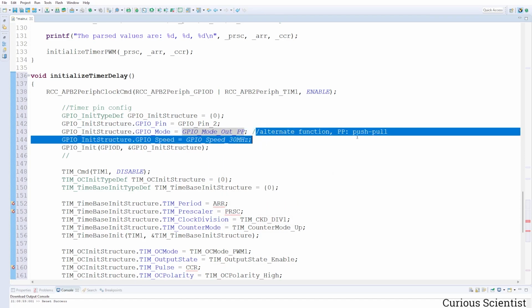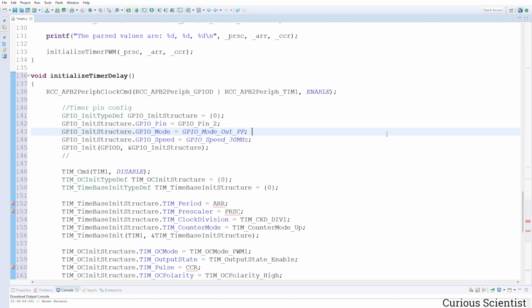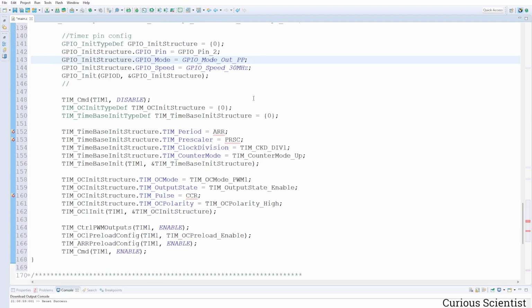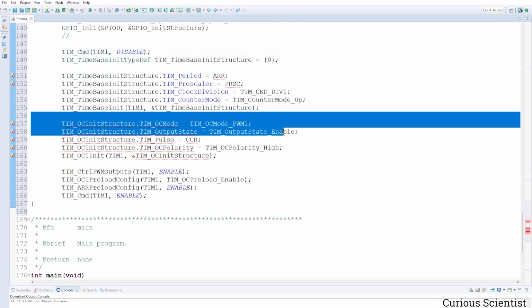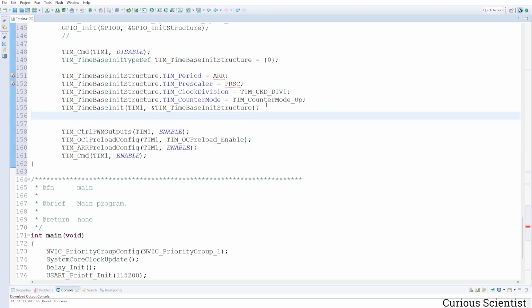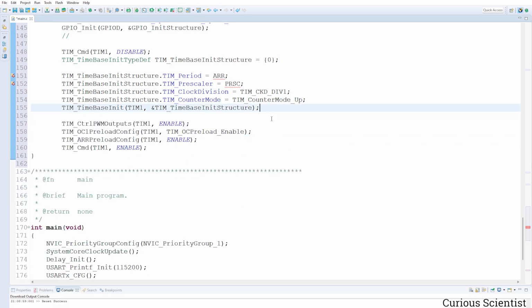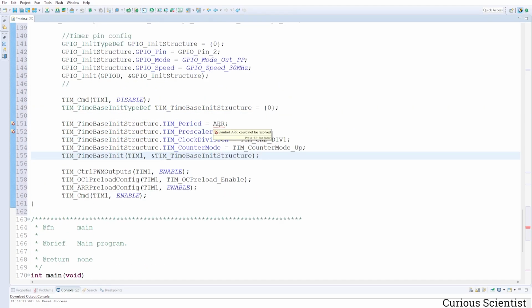And why I use this is because previously we used the GPIO pin as PWM pin. We don't use that as PWM pin anymore, we just want to toggle it, but not with the PWM, so that's why I remove this functionality. And together with that, I also don't need the PWM related functions or structures and so on. So I remove this guy here, and I remove all of these right here. So this is fine so far. And then I will just do this manually because of reasons. So the period will be 20,000.